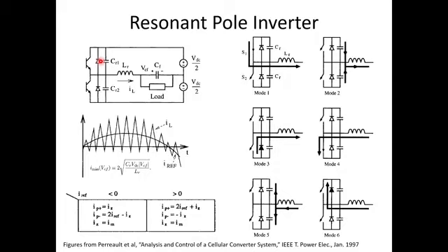So what's the idea here? We can assume that over any switching cycle, the voltage VCF across this capacitor is constant. It might vary anywhere between sort of plus VDC over 2 and minus VDC over 2, but within a switching cycle, I can think of it as quasi-constant, okay? So what are we going to do? Suppose I want to deliver a local average current over a switching cycle IL into the load filter combination, right?